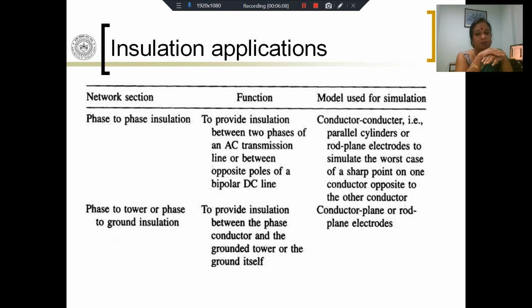You have to have an initiating electron, and that is related with the statistical time lag. And then you need the adequate time for the Townsend mechanism to build up such that enough electrons are produced, enough primary electrons are produced in the gaseous medium, enough secondary electrons are produced by positive ion bombardment and other secondary processes, and then these two combine together to satisfy Townsend's breakdown criteria.